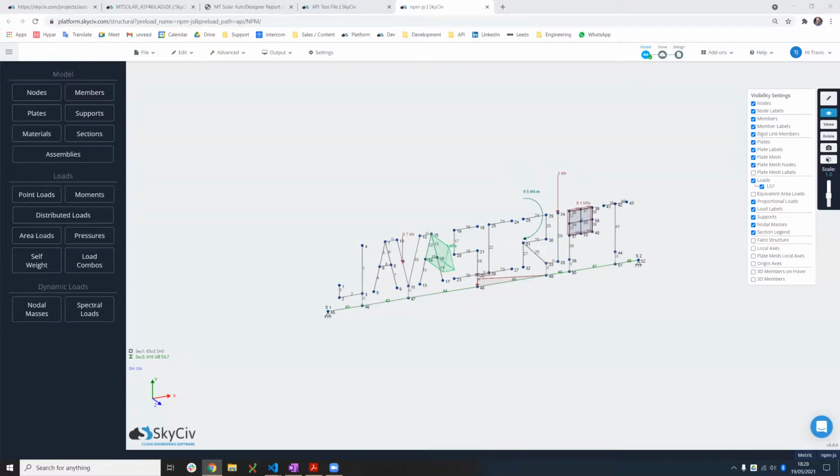So that's that one. And then, can wind loadings be modified to meet specific city ordinances? When you put in a location on our wind calculator, it will use Google to pinpoint that address. So it'll grab the snow loads depending on specifically what the code says. And I'm not sure if you can manipulate it. I think you might be able to override the design pressure, but without knowing what specific ordinance you're talking about, it's hard to answer exactly.